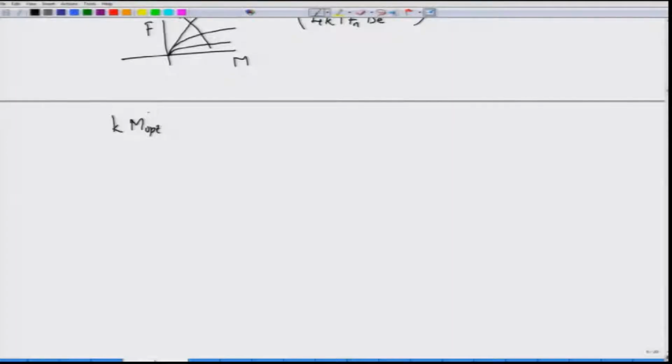You will end up with a cubic polynomial equation, which gives you the optimum value of the multiplicative term m. You get this term by going to the equation for the APD noise variance and then differentiating that with respect to m and setting it to 0. I will just leave it as an exercise for you to do that.